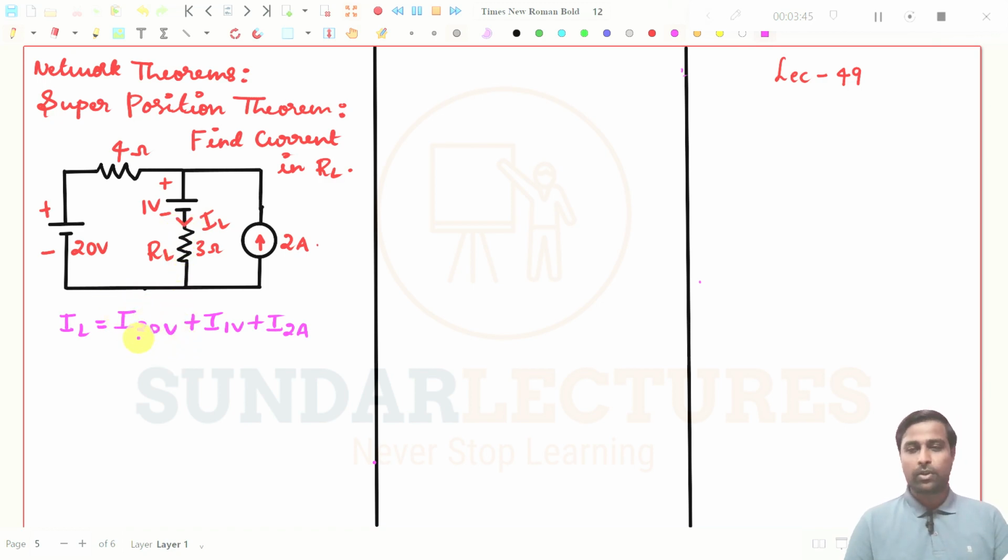That is nothing but I by 20 volt. Then, for the second case, you activate the 1 volt source and deactivate the 20 volt and 2 ampere sources. Then find the current through this 3 ohm resistor in this direction. It may be positive or negative, and that is I by 1 volt. Then, to find I by 2 amperes, you activate the 2 ampere source and deactivate the 1 volt and 20 volt sources. Find the current through this 3 ohm resistor in this direction and sum up all the values. You will get the current in this 3 ohm resistance.